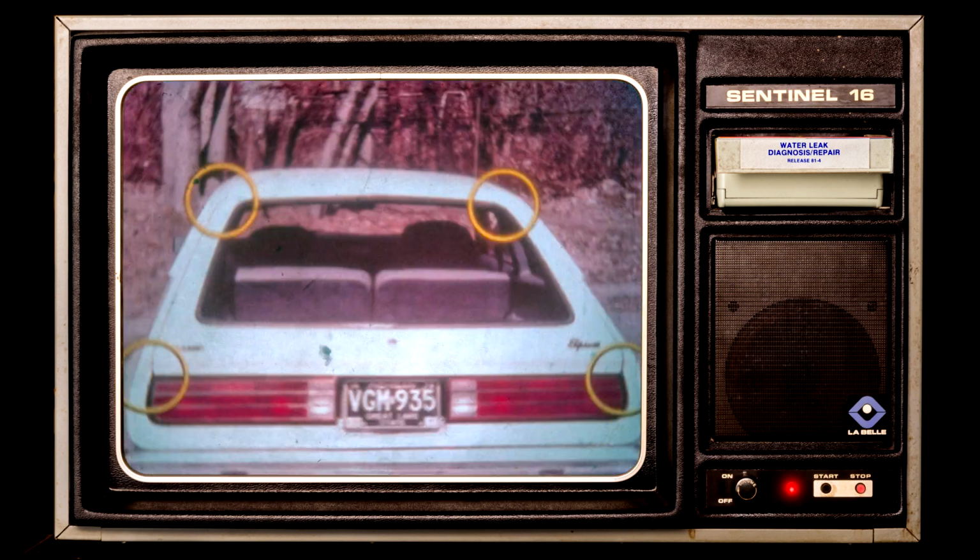A quick check for stains indicates that the water is entering the vehicle near the bottom of the rear hatch. Now we simply need to pinpoint the leak. There are a couple of things that we need to check. The hatch alignment should be checked at the areas highlighted here. Ours appears to be properly aligned, so we can continue the visual check.